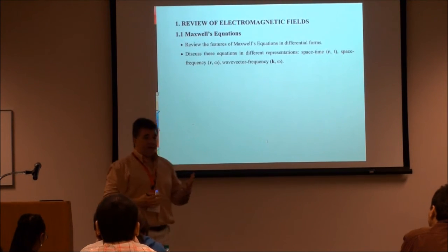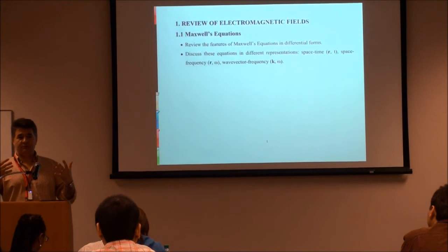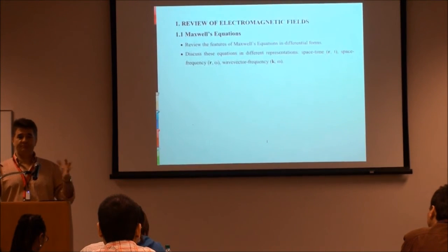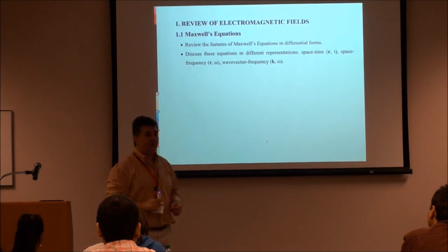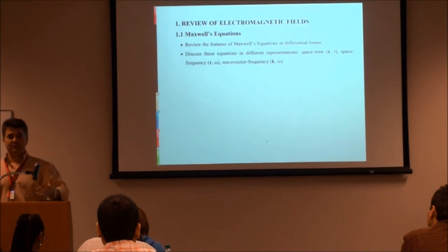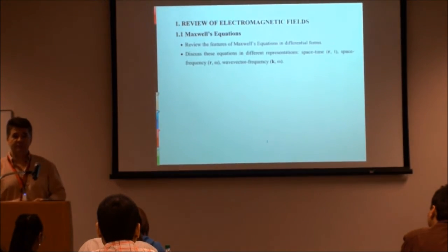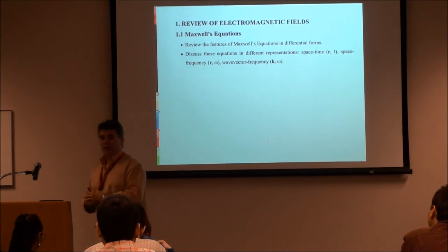The Fourier transform means that I can take a signal and decompose it into a summation of cosines and sines, with varying frequencies, amplitudes, and phases, which means that I can take now the problem, solve it for each frequency, and add up the results. Again, the superposition principle due to the linearity of the problem.